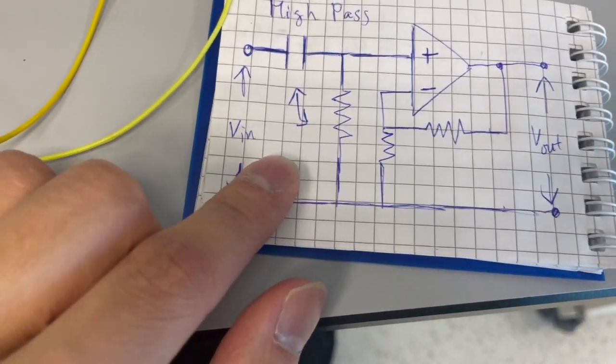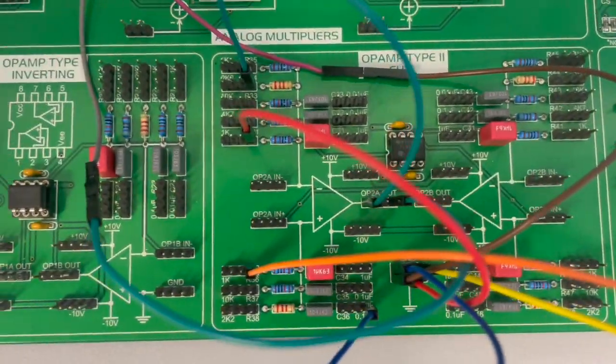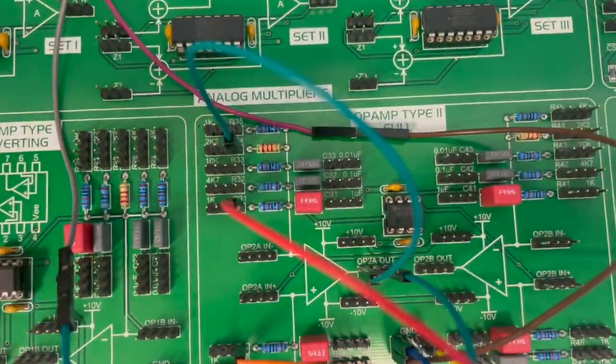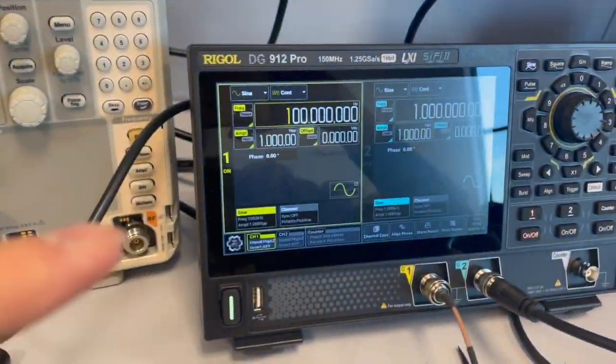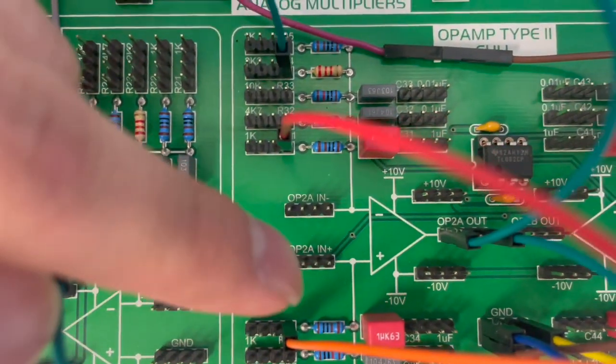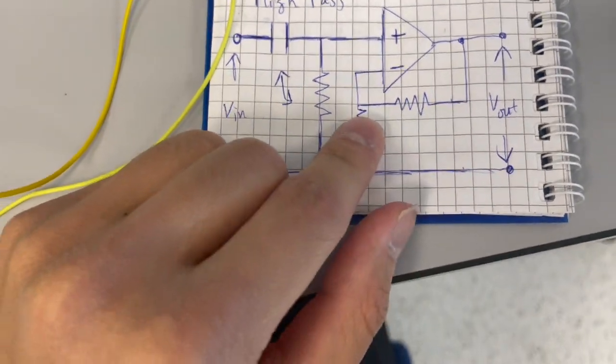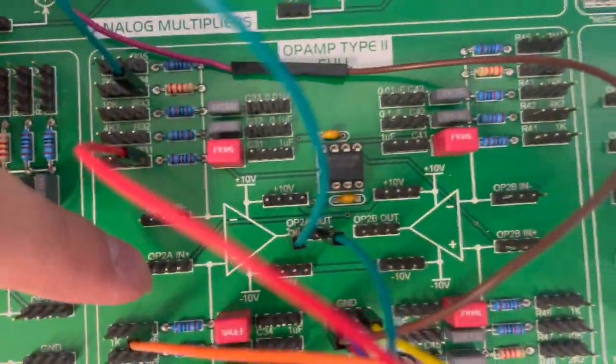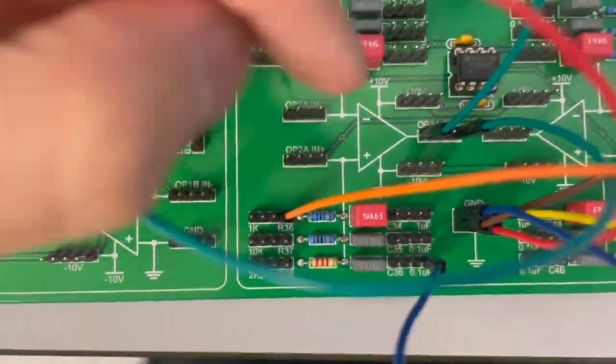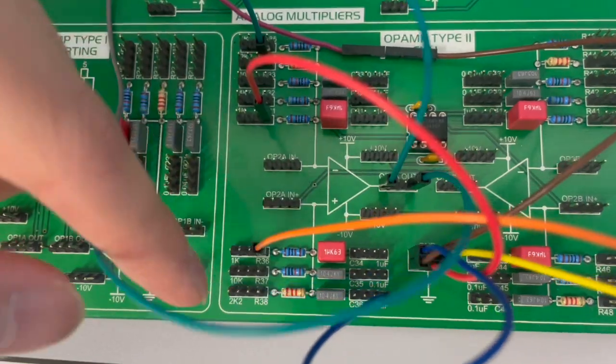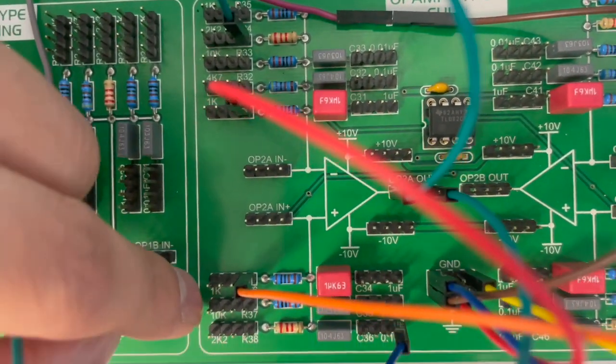So let's first build the low pass filter. As previously, let's start with non-inverting. For non-inverting, we connect the input from the signal generator to the plus, and the minus should be connected to the feedback loop with two resistors and to the ground. So what we do: plus, the orange wire. Remember the orange line was from the oscilloscope or the function generator. We put a 1K resistor to the input.